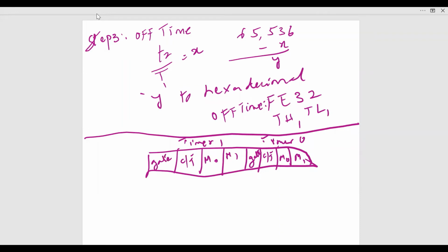So we want to use a timer for the programming. I want to use timer 1, and in timer 1 I want to go for the mode 1 operation. So you all know there are 4 modes: 00, 01, and so on. Why I prefer this mode is, in this mode the microcontroller operates as 16-bit, because the timer on time and off time are 16-bit. Hence I have chosen this mode selection. So I'm using timer 1 in mode 1.